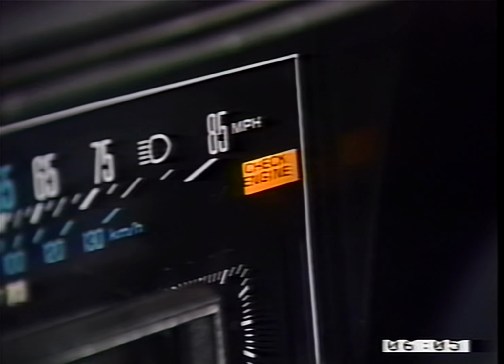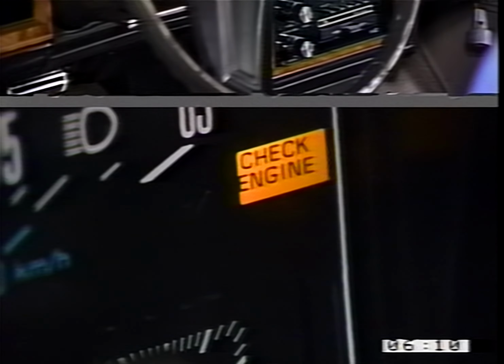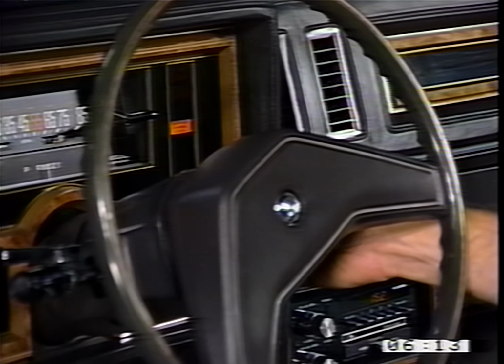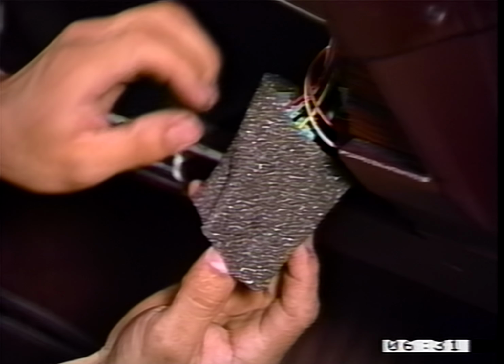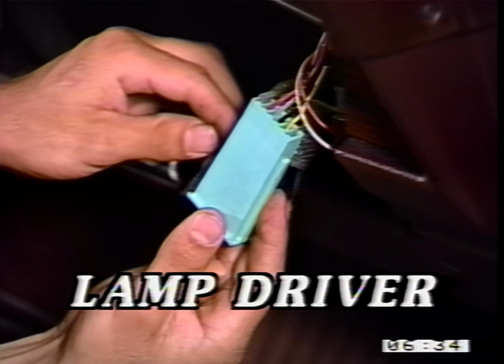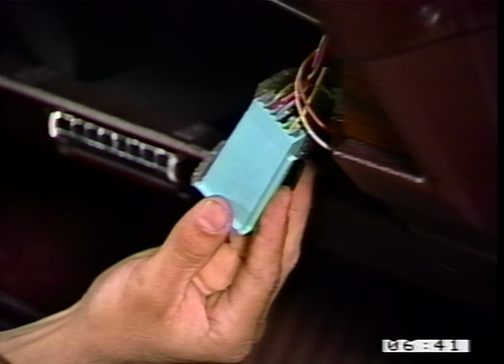The GM C3 system was first introduced with a driver warning lamp called a check engine light. This lamp was changed on all later models to read "Service Engine Soon." The ECM lights the lamp after being alerted to a problem in the system by the sensor. The lamp remains on until the problem is fixed. The ECM controls the service engine light in 80 and 81 applications. An electronic relay, also called a lamp driver, is found on later versions. The lamp driver illuminates the service engine soon light even if there is a complete ECM failure.